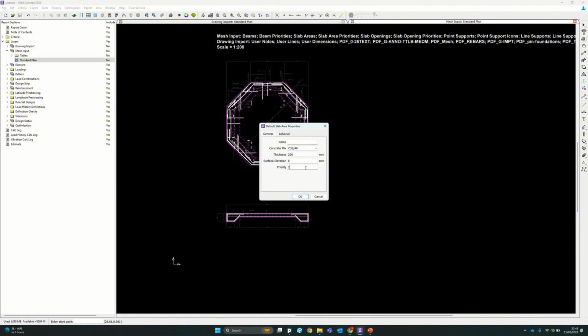That can become very tricky if you're, say, modeling downstand beams or upstands as well, or steps in slabs where, say for the downstand beam, if you model the priority possibly back to front, you could end up with, instead of the slab being modelled as the flange of the beam, you could end up with a situation where the downstand is just the only area of the beam that's being utilised and the slab is completely ignored, i.e. you end up with a downstand beam that has no flange and therefore is extremely underutilised.